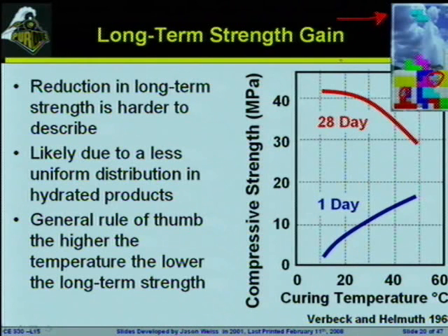So one of the things we have to be really, really careful about is if the temperature is too hot, what we're going to see in these really, really hot systems is that our concrete is not going to be gaining the strengths that we expect it to be gaining.